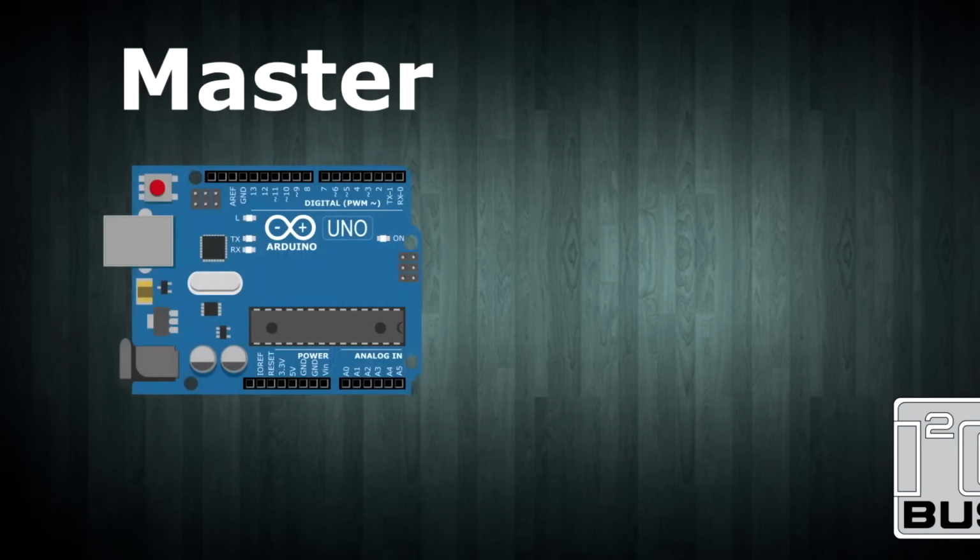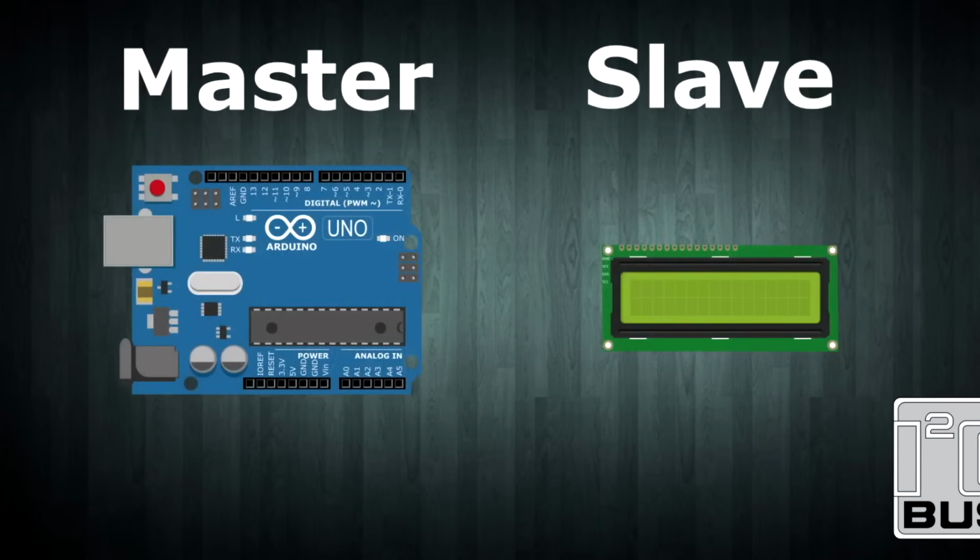Communication with I2C is also based on the master and slave relationship. For example, while our Arduino board is a master, our LCD screen is a slave, and we control the slave through the master. In addition, each device used in the I2C protocol has its own address. For example, like 0x27. We will use an address like this when using our LCD screen. In this way, we will prevent data from being lost while transferring our data.